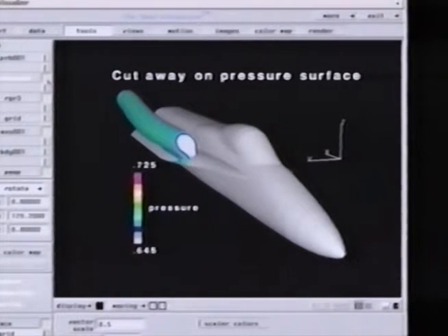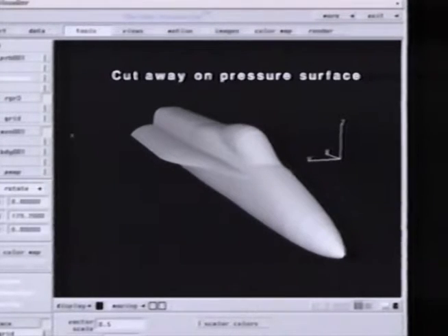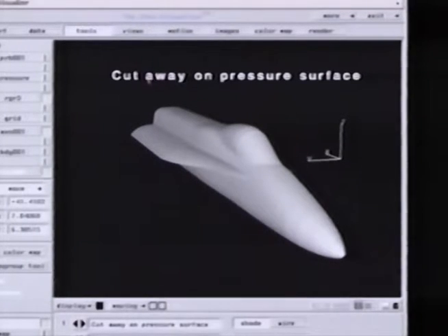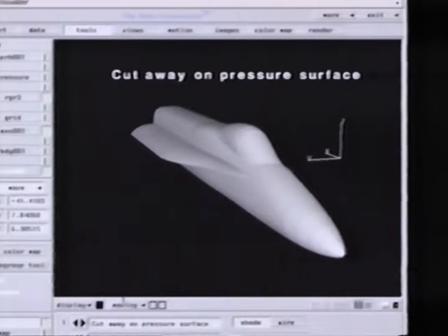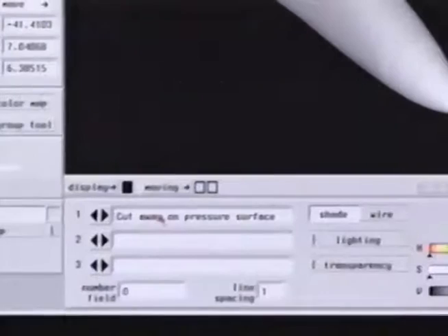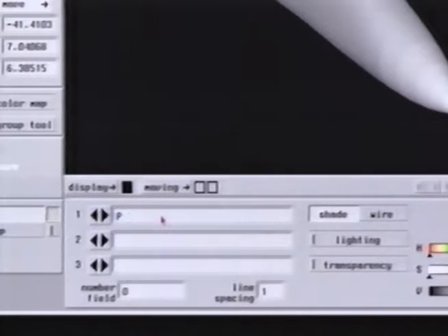Thus far, we've focused on methods for analyzing scalar data. Using techniques we've employed previously, let's move on to a tool designed for interpreting vector results. After simplifying the 3D viewport, we select the Text tool. We'll change the on-screen annotation to properly introduce this vector-oriented visualization technique. It's called the particle system. It produces both steady-state and time-dependent particle traces.